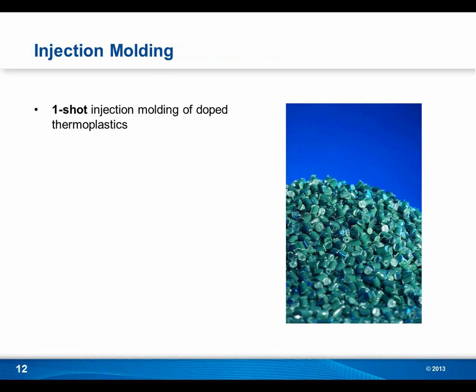Don, I wanted to bring you in right here. Why don't you talk a little bit about one-shot molding and how it's different than two-shot molding? Well, Stefan pointed out that the two-shot molding process can be a fairly complex tool. The mold itself has to have cavities for both types of plastic in it. In this case, you're talking about a plateable plastic and then a non-conductive plastic. Laser direct structuring allows you to use a single type of plastic, in a single shot mold.